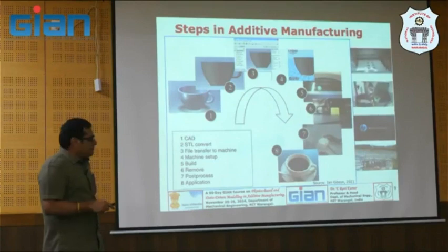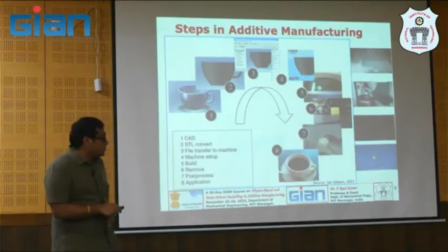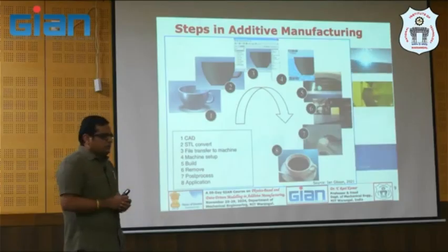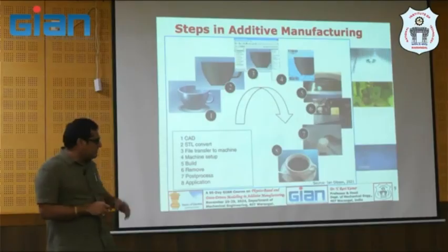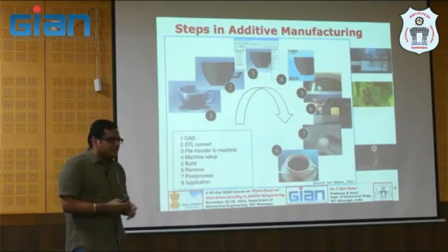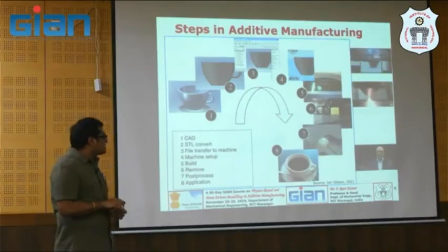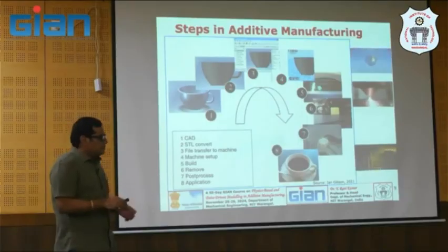Now, if you are not satisfied with the mechanical properties or microstructure, which you want to improve, you compare the as-built versus the post-processed component. Why? Because your application demands it, right? Based on the application, post-processing can be a heat treatment, a surface treatment, or hipping.